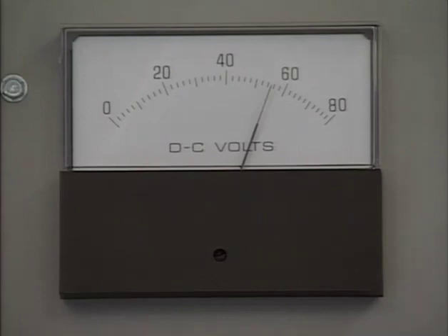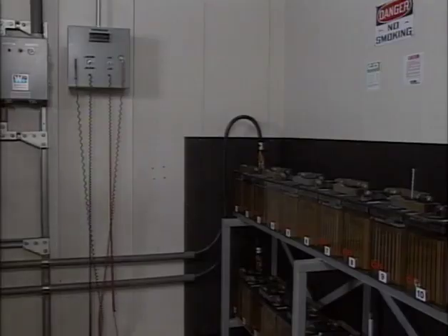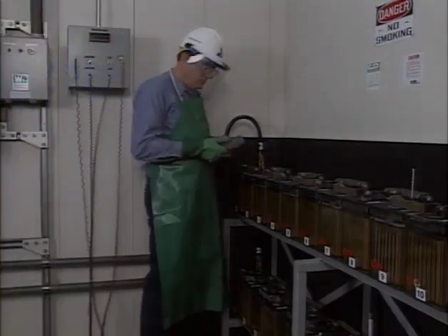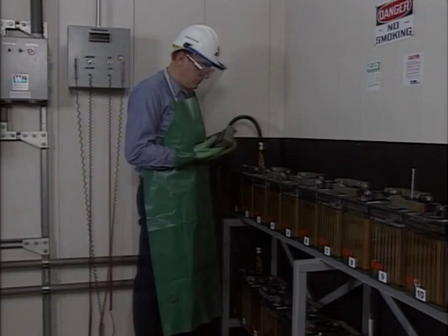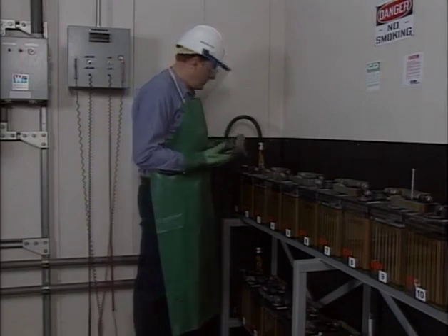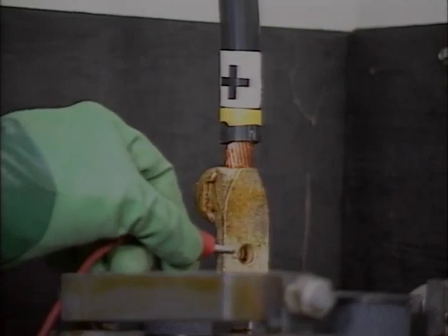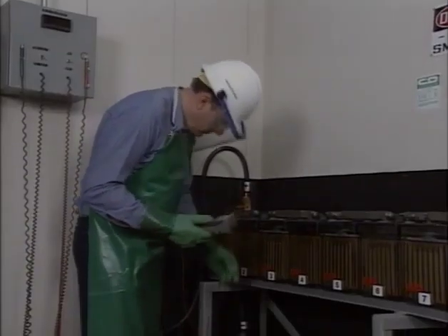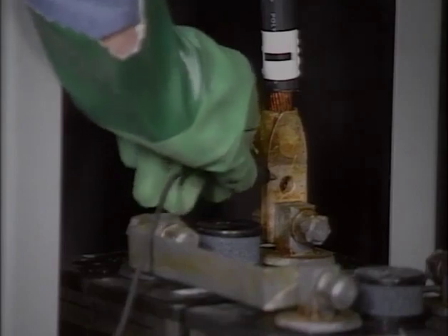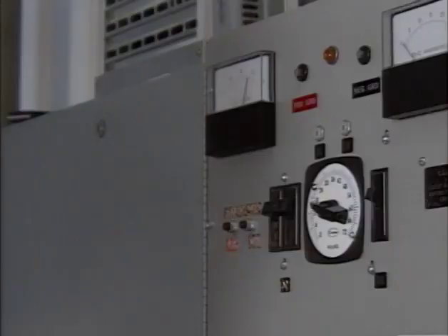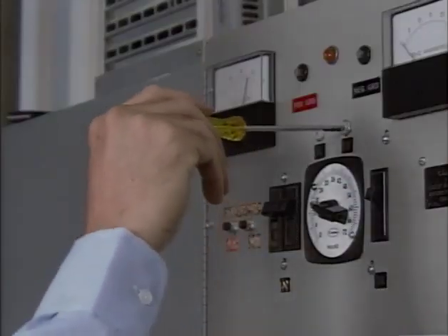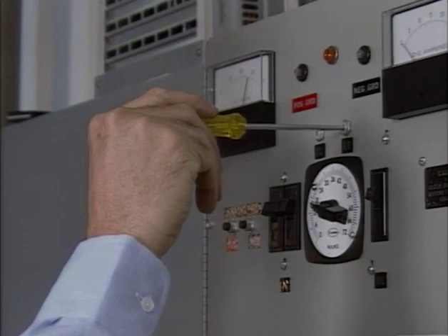It should be noted, however, that many utilities feel that a charger's analog voltmeter is not sensitive enough to be relied on for critical voltage adjustments. In this case, the DC voltage output can be verified by connecting a precision voltmeter or multimeter across the positive and negative terminals of the battery or across the charger output terminals. It's often recommended that the voltage be checked at the battery rather than at the output terminals of the charger because of the possibility of a slight line voltage drop between the charger and the battery. If necessary, the equalizing pot is adjusted to get the precise charger output required.